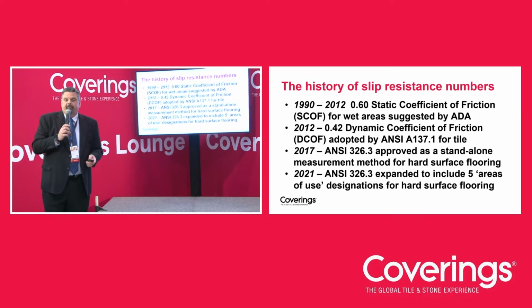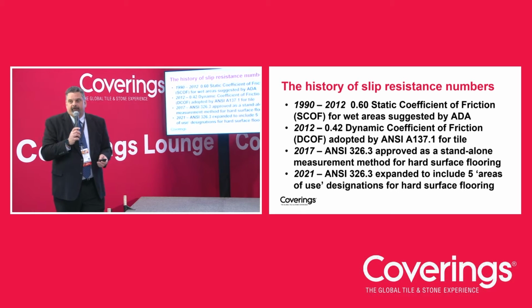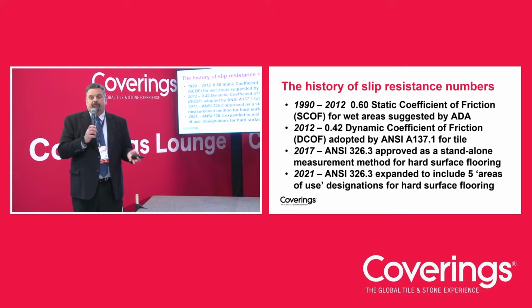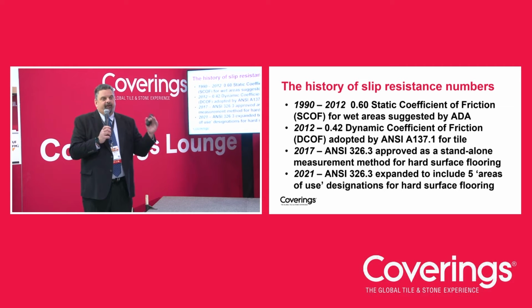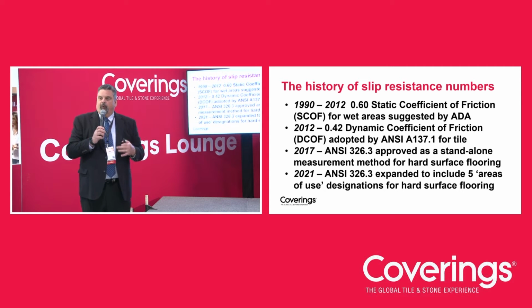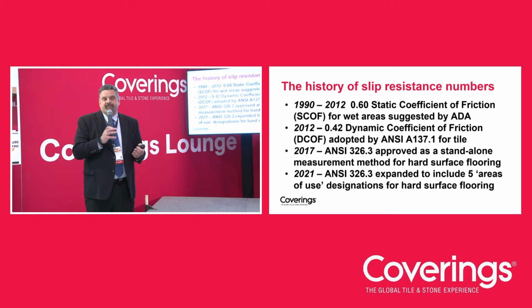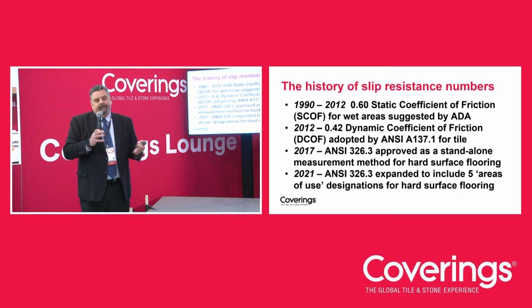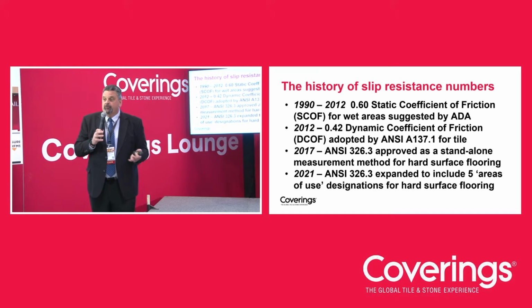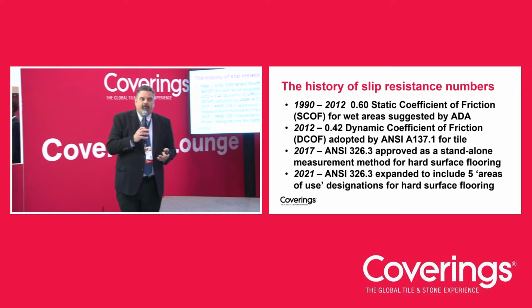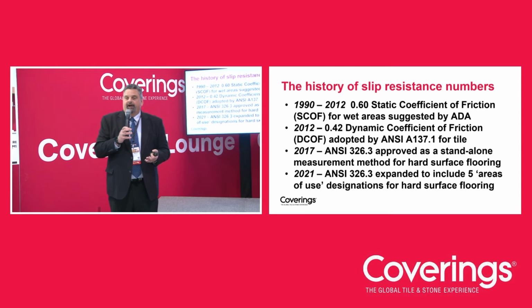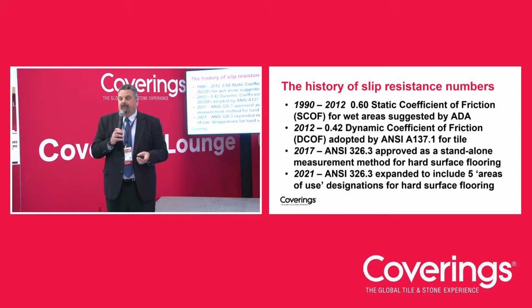So, a little bit of background on where the industry has been as far as slip resistance. Slip resistance has had a few different attempts to quantify it. And the main thing that we've hit upon over the years is called coefficient of friction. A coefficient of friction is just how much resistance there is to something sliding across the tile. In a practical sense, that would be your shoe, but in the lab, we have to make it in a way that we can somehow measure it and quantify it. So we do that with a variety of devices.